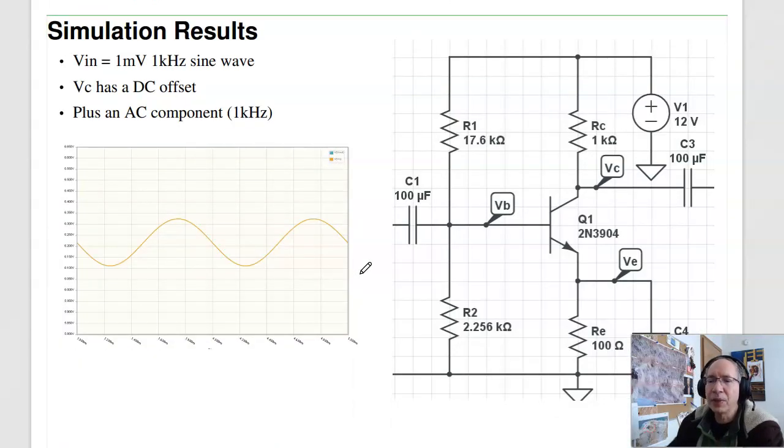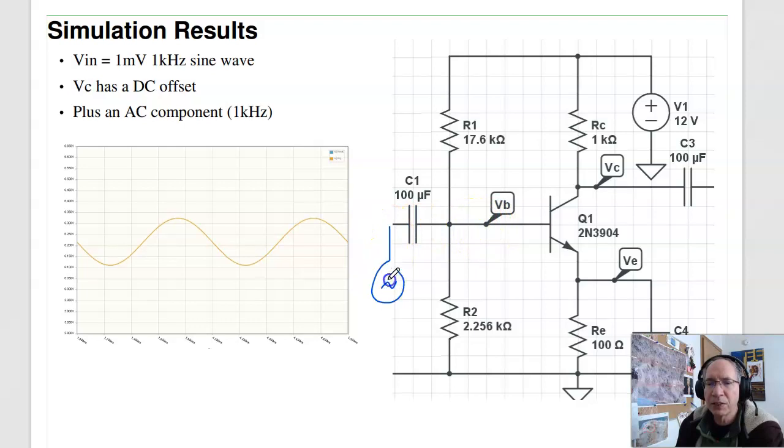In Circuit Lab, I can check. Suppose I build this circuit, I want to find the 2-port model. Well, to find A out, if I look at the different signals, this is a 1 millivolt sine wave. All the voltages in the circuit have a DC term, that's the DC analysis, plus an AC term, that's the ripple, that's the AC analysis. And by superposition, I'll have 2 terms, DC plus AC. The capacitors block the DC, so all I really care about is the AC part.